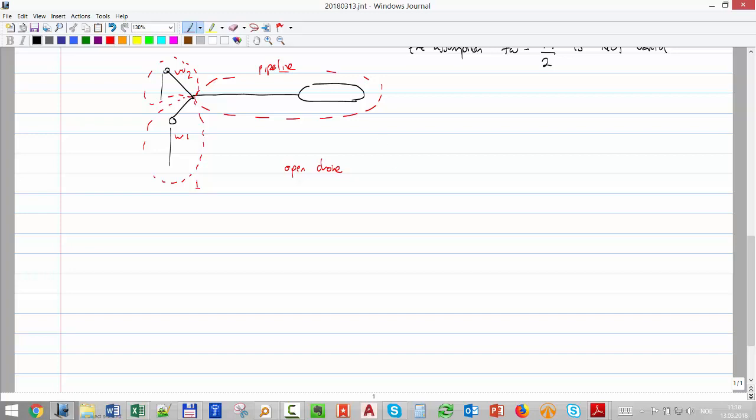Okay, so I'm going to start with well 1. And well 1 looks something like that. And here I have a pressure that I'm going to call P junction, and I'm going to put just 1 to be sure that it's as seen from well 1. It will be the same pressure, right? But I'm looking from different locations. So if I were to plot P junction 1 versus the Q of well 1, the rate of well 1, how is it going to look?